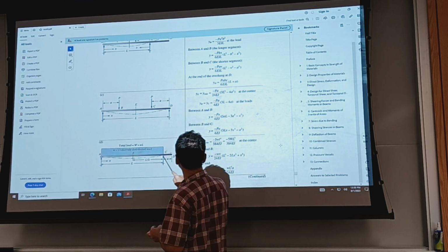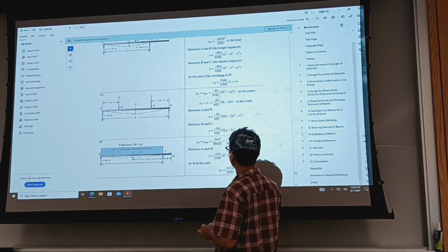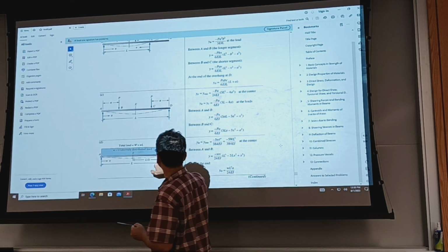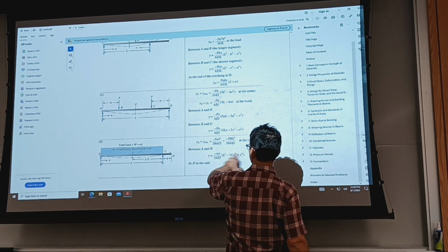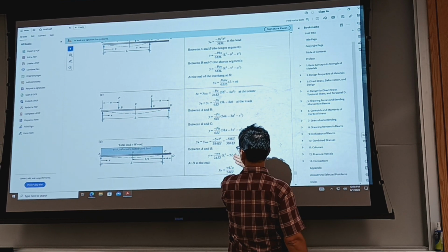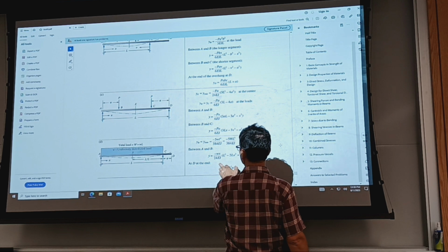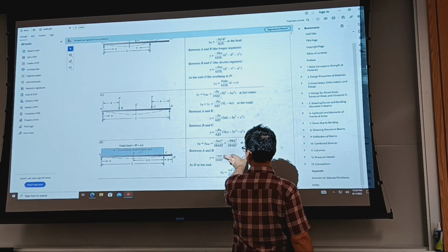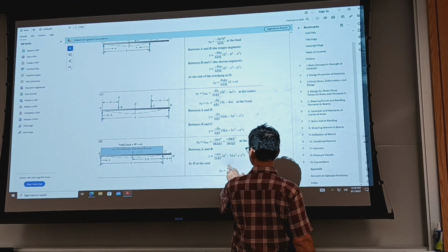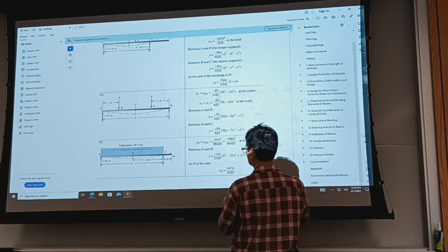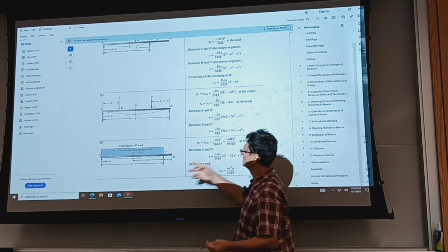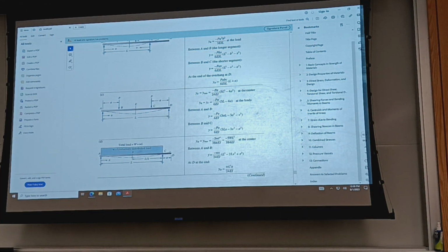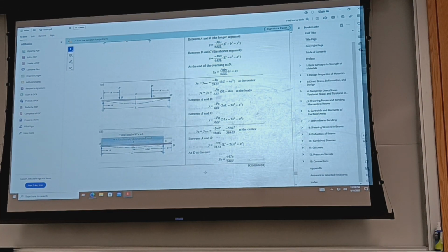And we can actually derive this because let's see, if you're to evaluate a slope that is delta at C, you take the derivative of y, it says between A and B. So the slope at A is the slope at C. So you evaluate it and you make x equals 0. So what does it get you? It would be the derivative of this, and these go to 0, so it'll be W L cubed over 24 E I, right? And then times A. So yeah, we were able to quickly prove where this last equation for deflection at D came from.